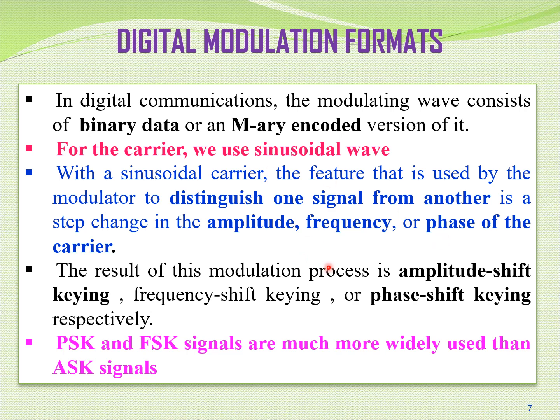If we use amplitude, we call it amplitude shift keying. If we use frequency, we call it FSK. If we use phase, we call it phase shift keying. And PSK and FSK signals are much more widely used than ASK signals because of the noise immunity of PSK and FSK schemes compared to ASK.